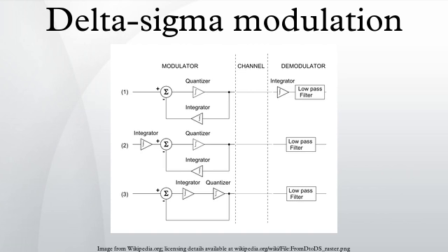Decimation structures: the conceptually simplest decimation structure is a counter that is reset to 0 at the beginning of each integration period, then read out at the end of the integration period. The multi-stage noise shaping structure, or MASH, has a noise shaping property, and is commonly used in digital audio and fractional-N frequency synthesizers. It comprises 2 or more cascaded overflowing accumulators, each of which is equivalent to a first-order sigma delta modulator. The carry outputs are combined through summations and delays to produce a binary output, the width of which depends on the number of stages of the MASH.